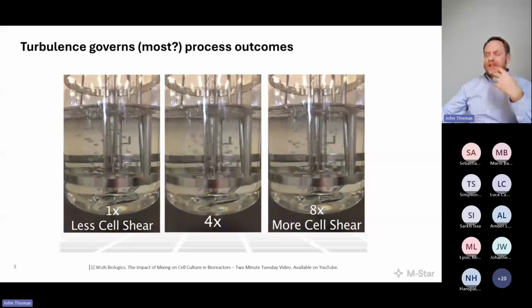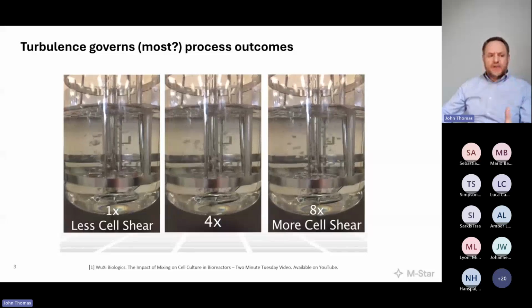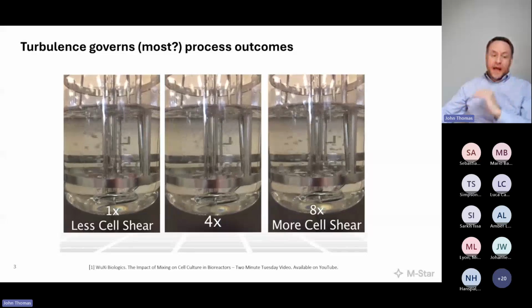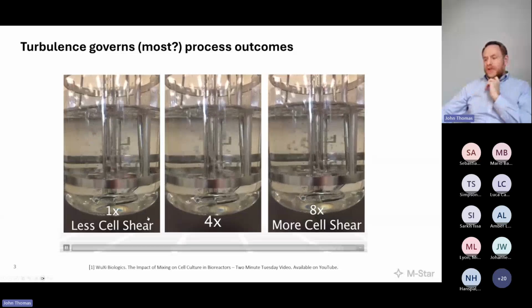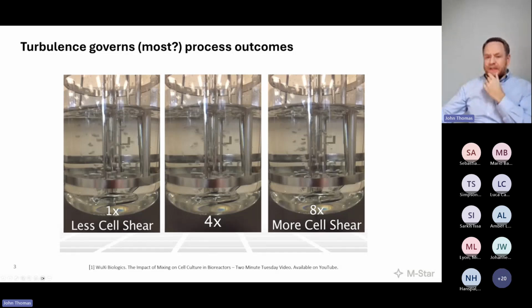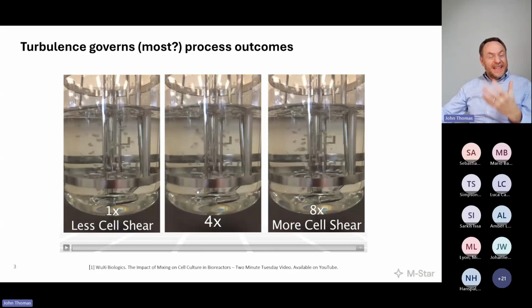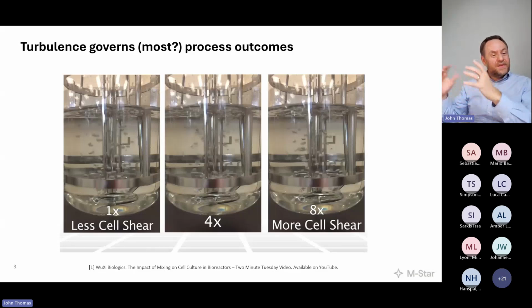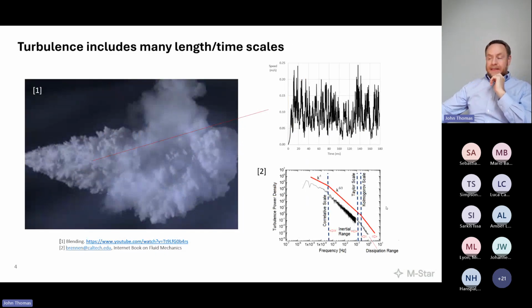So turbulence spectra and energy dissipation rates associated with that turbulence drive a lot of our process engineering. Shear, etc., is not necessarily related to EDR, but it is related to velocity gradients. It's again a function of the fluid viscosity. Now, to be sure, the strain rate as well is related to EDR. They're linked. EDR comes from strain, but strain is calculated directly from viscosity. So this idea of turbulence prevailing throughout our process engineering systems is not a big claim.